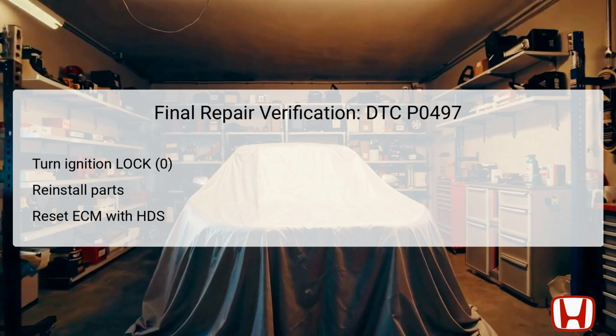Once troubleshooting has been completed and necessary repairs made, it is time for final repair verification. Start by turning the ignition switch to the lock position, ensuring all electronic components are completely powered down. All parts that were previously removed during troubleshooting need to be reinstalled correctly in the reverse order of removal.